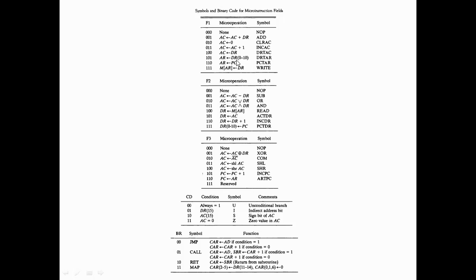And we just said that in our example, the main memory is of size 2048 into 16. So 2048 means 11 bits of address. That's why it is written here 0 to 10, so 11 bits of address. In the same way, 110 will be PC to AR, and 111 means write operation. That is, the contents of DR are written into main memory.